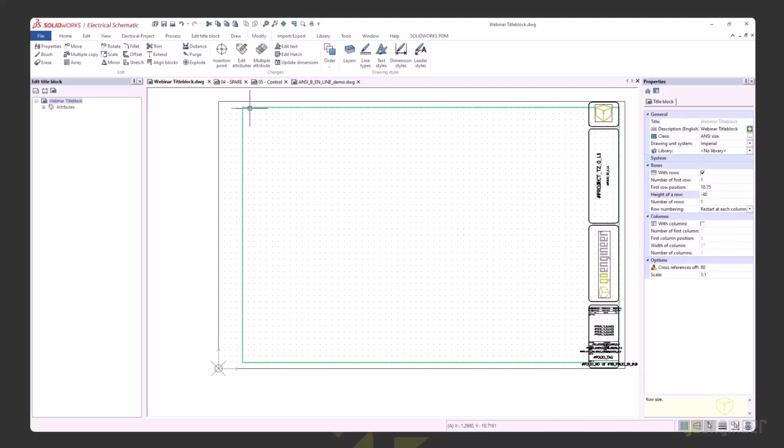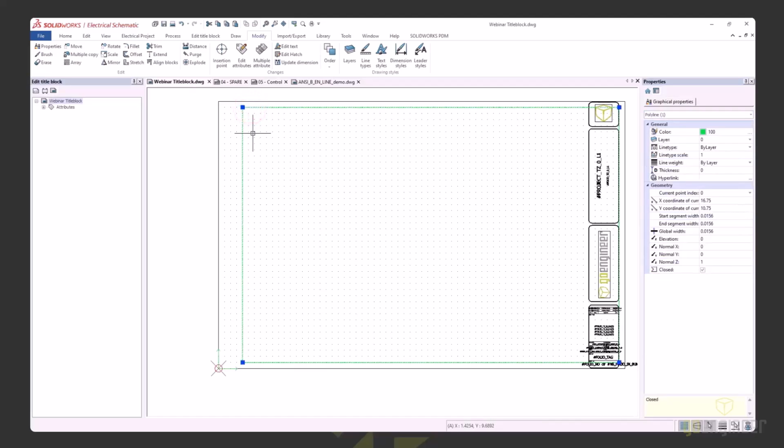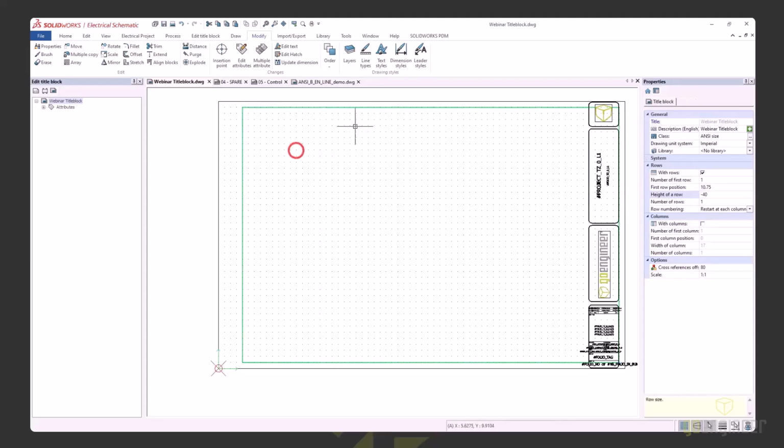So from here, I am now wanting to drop down, and maybe I want to have each row be about 3/4 of an inch. All right, so here's what I'm going to do. I am going to say negative 0.75, and that is going to be my distance. Now, I don't know how many rows I'm going to have, so I'm just going to go ahead and say maybe it's 15.